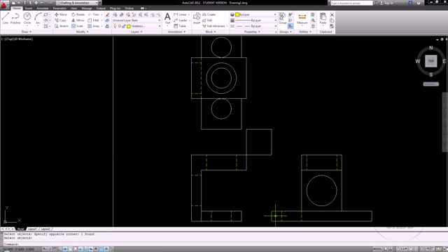I'm going to go ahead and erase that line, and then I'm going to copy both of these over, and I'm going to just point to the right, and I'm going to type 30, enter, 60, enter, because that's where they're lined up. So with this one here, I was able to line up everything mathematically as opposed to going through and lining everything up with the miter line. I do need a hidden line from here to here to represent the rest of the bottom of my edge, and that is pretty much it as far as hidden lines and stuff like that is concerned.